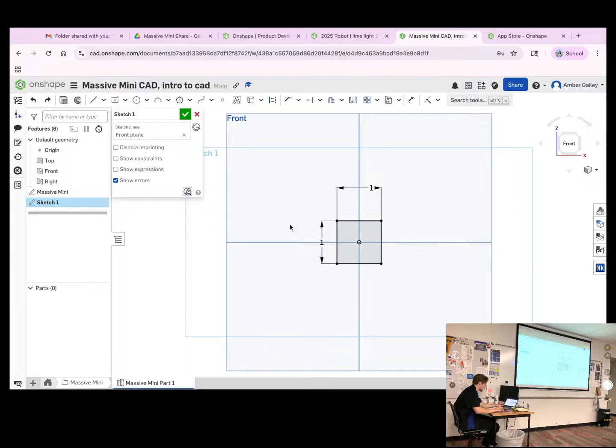I mentioned this earlier, but making sure you have space to screw in bolts and rivet heads, and so they're not rubbing. Our elevator, every time we went up and down, created a ton of metal shavings. It was like the inside of a snow globe every time we ran it. And having metal shavings come out of your robot every match is not good.